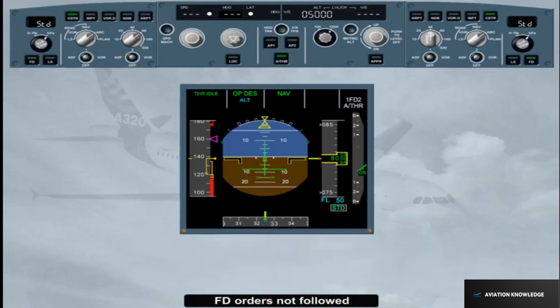Both FDs disengage when the airspeed reaches VLS-2 knots. But if speed brakes are extended, the FDs disengage between VLS-2 knots and VLS-19 knots, depending on the speed brake position. The autothrust effectively reverts from thrust idle to speed, and the thrust is readjusted to recapture the target speed.